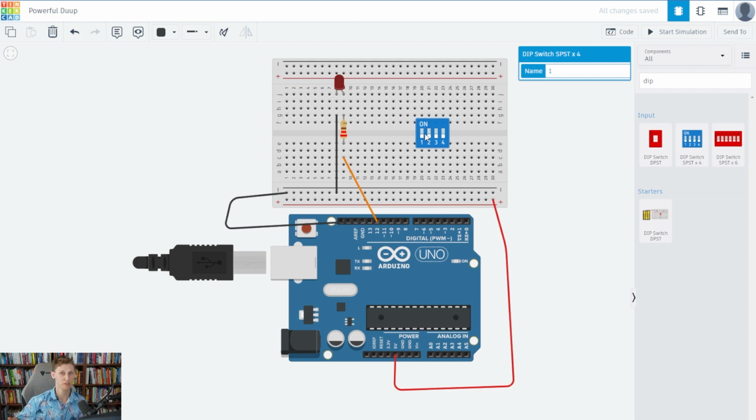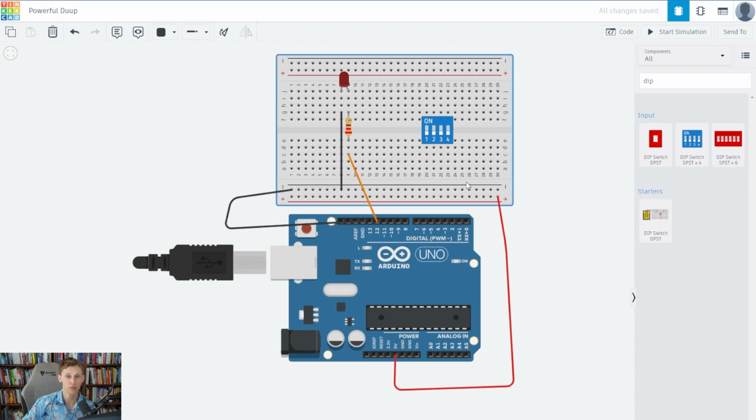Instead of yesterday's useless blinking on and off, which is good for understanding how coding works but not really good in practical application, we're going to need to use a pin on the board as an input. We need some pin that's designated to read as an input to say, hey, when the value on this pin changes, turn it on or turn it off. The input pin we're going to use today could be any one of these pins realistically, but for our purposes, we're going to use pin 2.